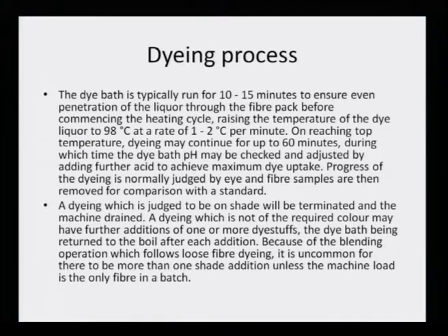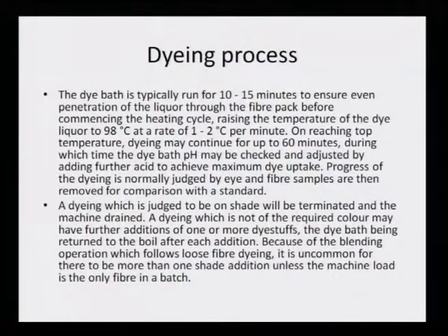So, three things have come up. First thing is that temperature is very important. Second thing is that pH maintenance is very important, and the third thing is that 1 hour is more than enough for dyeing. Progress of dyeing is normally judged by eye, and fiber samples are removed and compared with the standard.